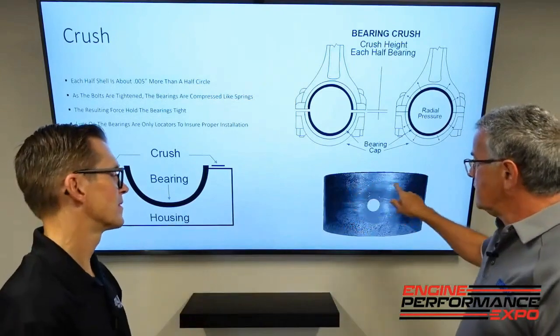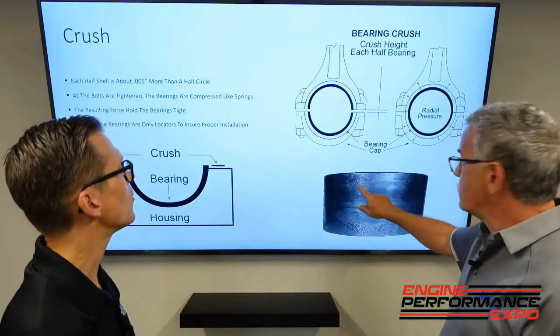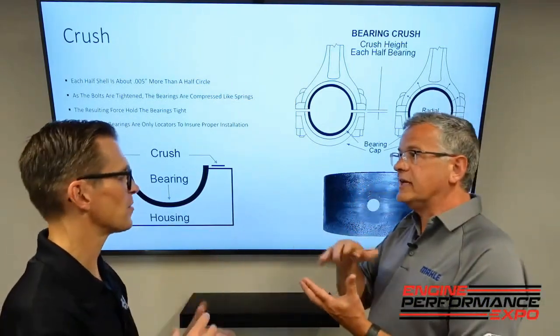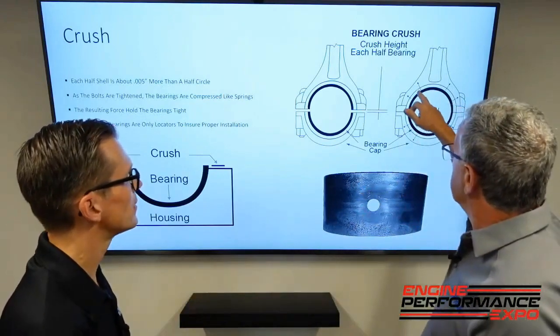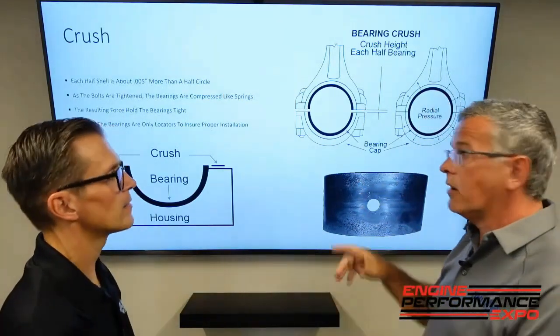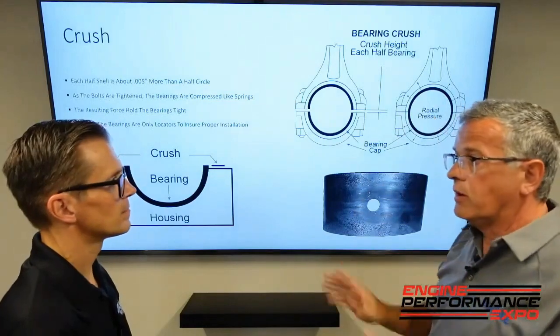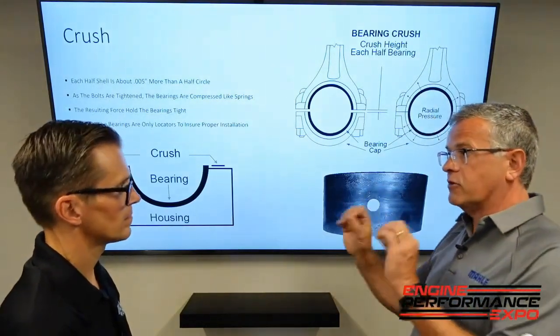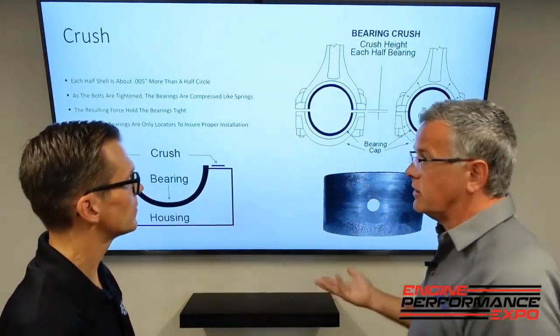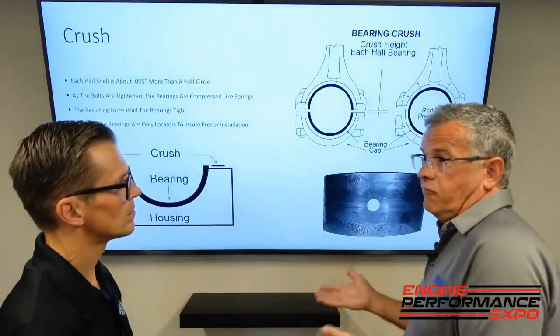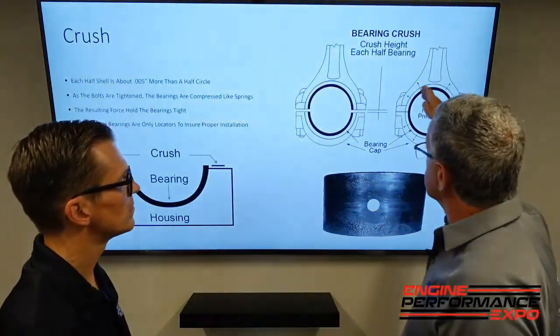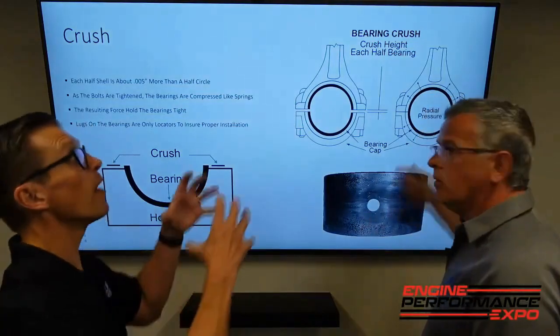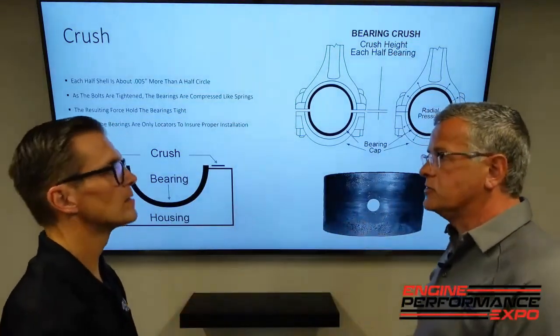Reduce the crush, and then the bearing walks around and causes fatiguing on the back, a little fretting and all that. Typically, you can get it on the connecting rods as well, where on the point loads it will start to fatigue and fracture and fret the connecting rod. So you can actually decrease the life of the rod because you're creating stress points, because it's moving.